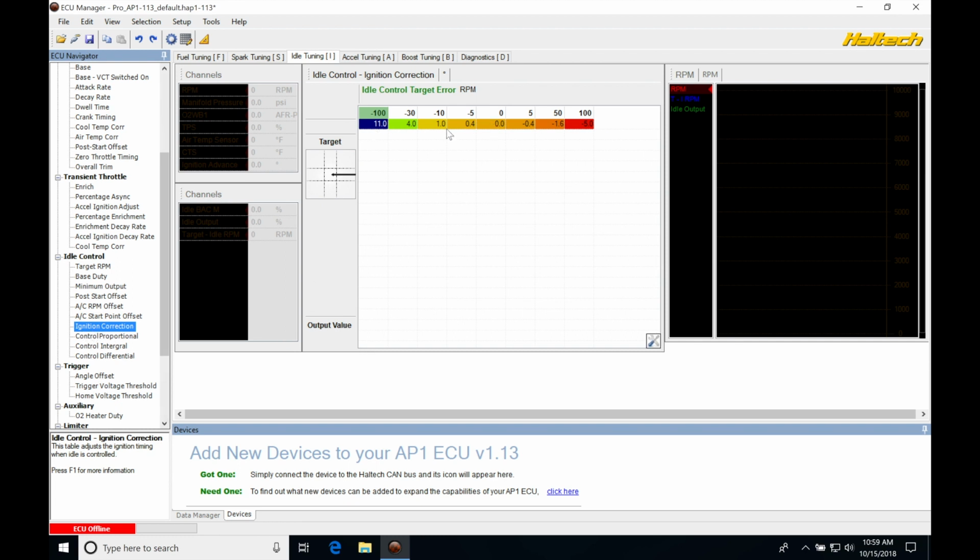The values that we have in here are going to be ballpark to start with. If you find that your engine is very sensitive and it wants to dip down in engine RPM very quickly, that your idle RPM control here isn't going to add enough duty cycle to catch it, we're going to want to use ignition timing and be a little bit more, maybe more aggressive.